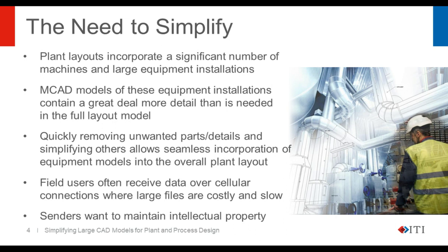It's generally far, far greater detail than you need in the plant layout, where perhaps you only need the model for clash detection, pipe routing, cable routing. Also, due to the sheer size of the plant layouts themselves and the volume of data represented, the plant design systems are often developed to handle primitive shape representations of the equipment, things such as cylinders or boxes, and not the full mechanical CAD representation.